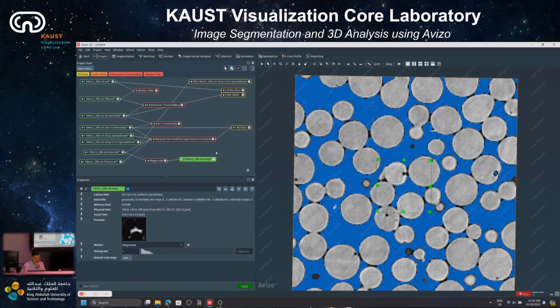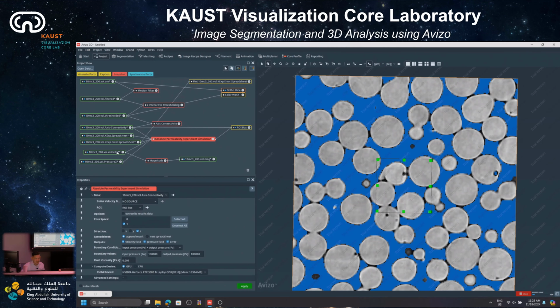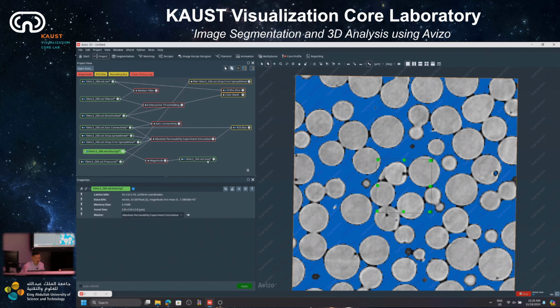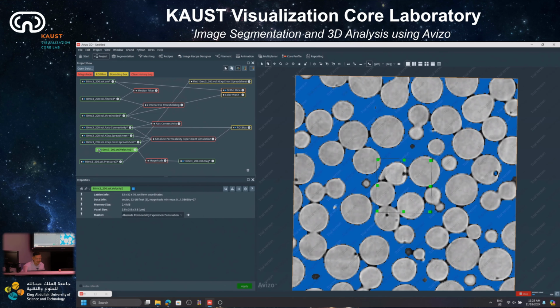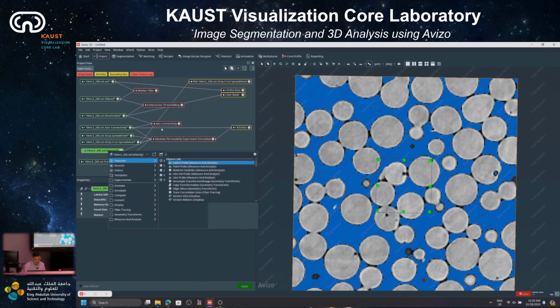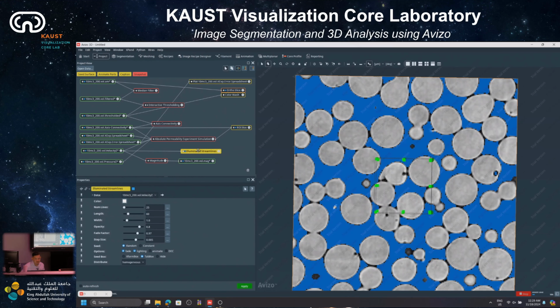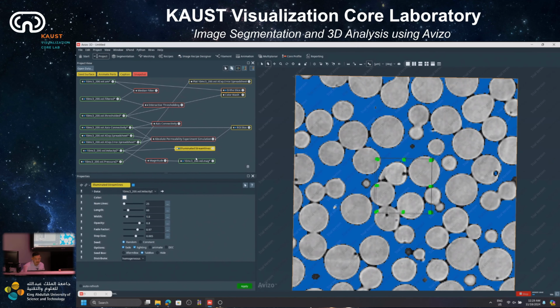Now I'm gonna visualize the velocity using the illuminated streamline. So right click on the velocity tab and type illuminated streamline. It's a display, to visualize the display. In illuminated streamline, you can connect the color field to the magnitude.